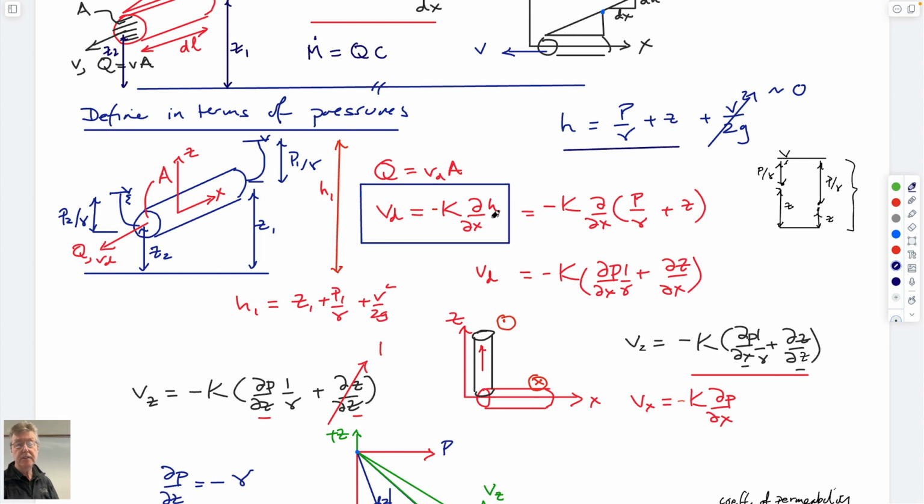pressure and elevation. So this term here, we could substitute by taking this term here and merely adding it in here, in which case, if you take the differential outside, we have pressure over unit weight plus Z. And since this is operated on by a differential, we could differentiate each of these terms. So this differential is equal to dP/dx, just this. I guess it does need that other term: 1 over unit weight, and dz/dx.